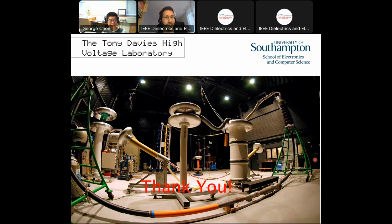Yes, this is a very good question, and that's something I take very personally as well. Of course, there's a general consideration that space charge is only a DC issue, but in my opinion, it is an AC issue as well. And that's one of the reasons we observe this lower breakdown strength for the AC. In my opinion, space charge comes into play and has a very important role in the AC breakdown as well. So yes, in my personal opinion, it's probably more important in the AC than in the DC. And that's a topic I'm trying to focus on at the present time.